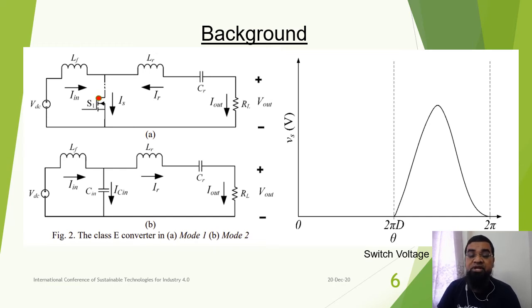Maybe your other components are very small and can fit in a very small, compact space, but this switch will be very large, and it will be very expensive. So this is a great problem with the class E inverter, which later researchers have tried to solve. Now say you are using this inverter in your laptop. If you need a big switch, the laptop size will be bigger. I'm just giving an example.